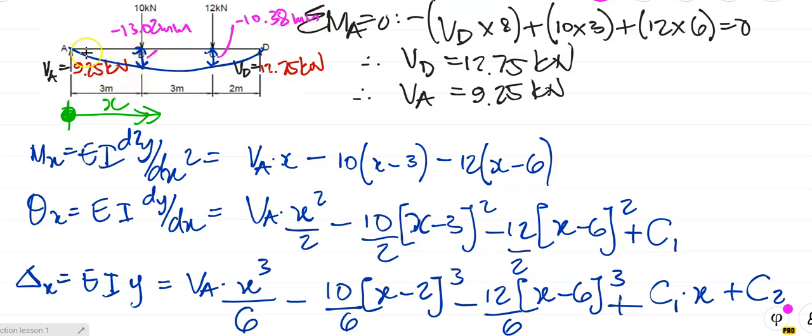So that's actually before the forms are removed, when the beam, remember in theory of elastic bending, is truly horizontal. As the form is taken away, as the beam is loaded up, it drops below the 0 line. The minus sign just means it drops below the 0 line. So from there to there is about 13 millimeters, and from there to there is about 10.4 millimeters. That's why it's minus.